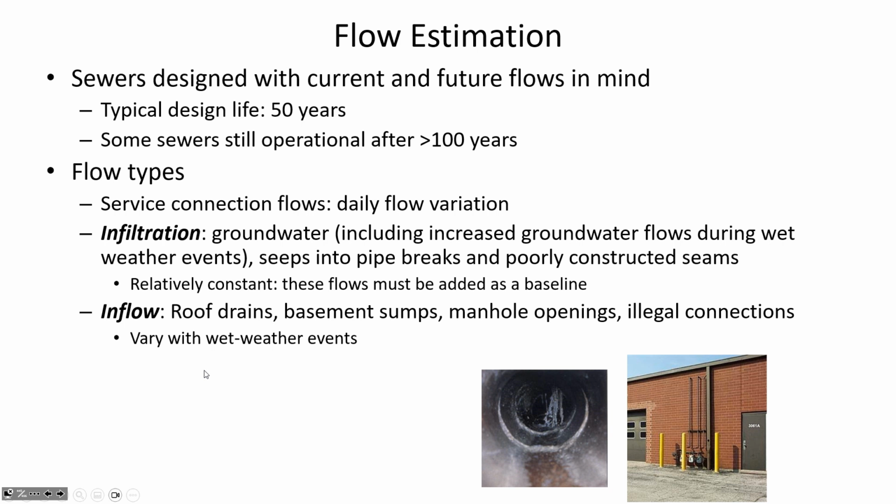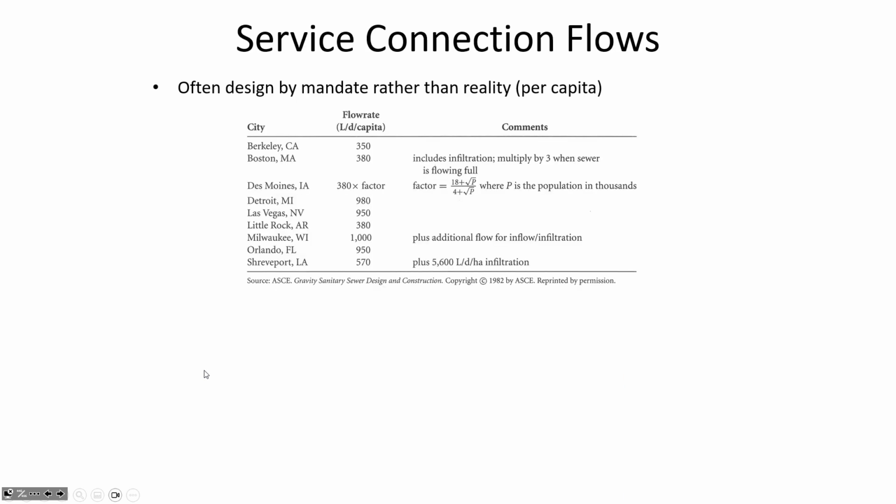So infiltration and inflow are additional increases in the water that's getting into a storm sewer that also add to how much capacity you have to allow in order to ensure that you don't have wastewater backing up into people's basements. And that can be the consequence of an undersized pipe, is that water backs up and it flows into the low point of somebody's house, and it's really a bad look for a city when a homeowner has thousands of dollars worth of damage and kind of a contaminated living space due to sewage getting in.